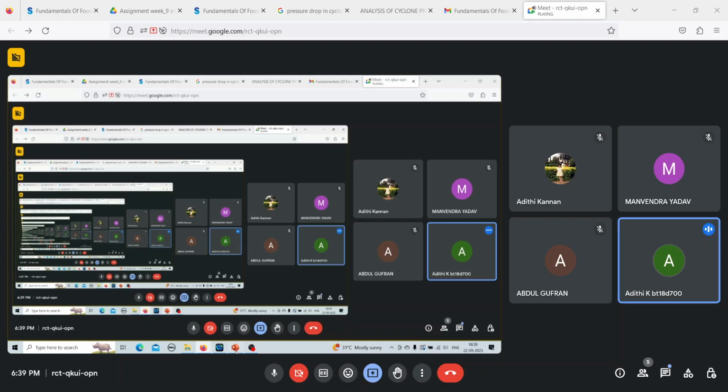So the de-stoner separates the stones from the product on the basis of difference in specific gravity. The stones, having a higher specific gravity than the product, do not move upon fluidization with the air. When you pass in air from the bottom, you have a fluidization-like process, where your lighter particles behave like a fluid and pass through easily, whereas your heavier particles remain almost stationary.